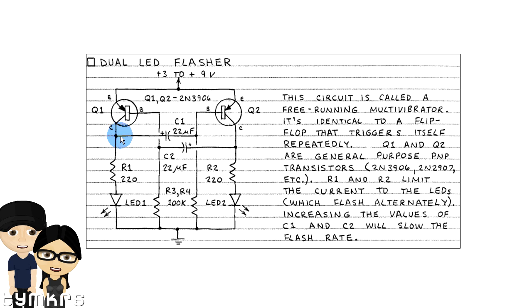And as they do that, the current that goes through C will charge up these capacitors here. And if you know anything about capacitors, you know that with AC voltages, it allows the AC voltage through. So assuming there's some sort of AC voltage here, the AC will go to the base of the opposite transistor, right? So we've got charge coming through here, charging up the capacitor, but also AC style, bringing up the voltage here at the base.